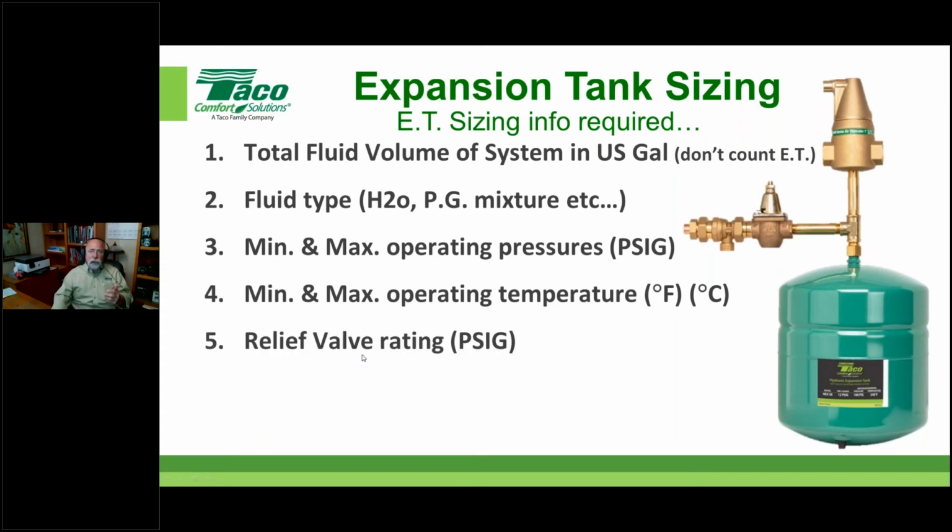Now, some people will look at this relief valve rating and actually size the relief valve based on some components within the system. Well, normally in a residential application, the number one thing we're worried about is that boiler. And most residential boilers nowadays will have a 30-pound relief valve. So we're going to generalize based on a 30-pound relief valve. But again, we need to know this information. We need to know what that relief valve is. This will help us when it comes to figuring out what that maximum operating pressure up here is going to be. Okay. Again, a system static pressure.